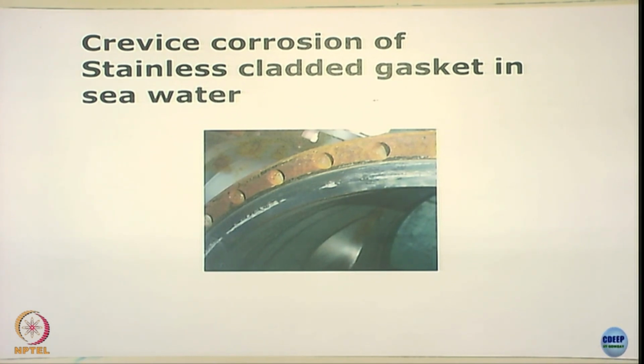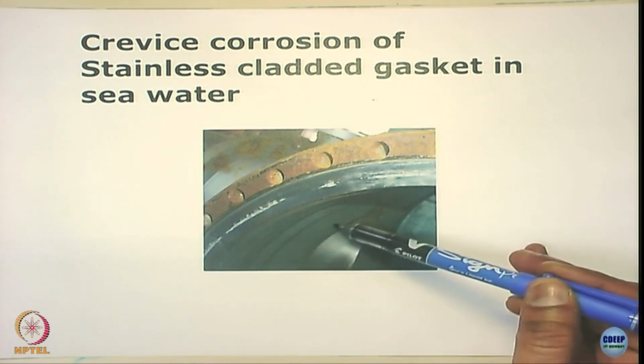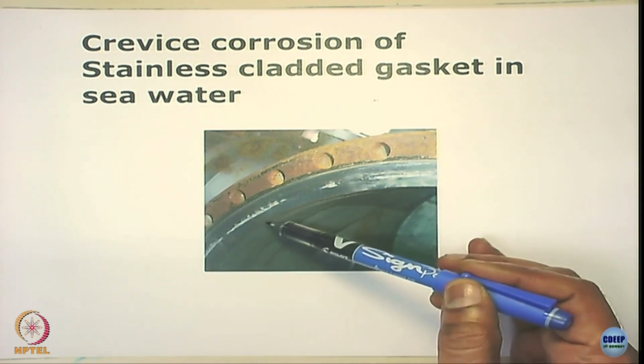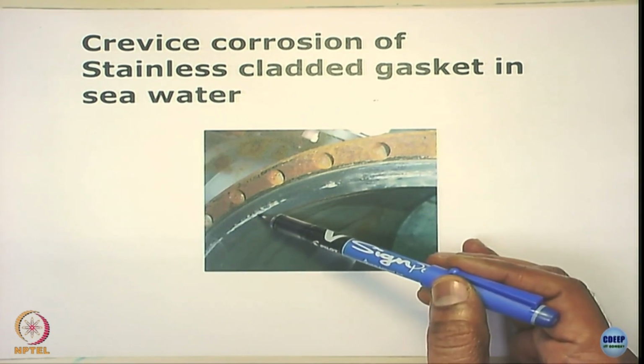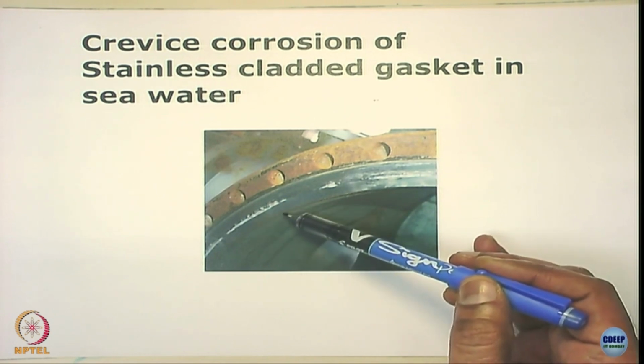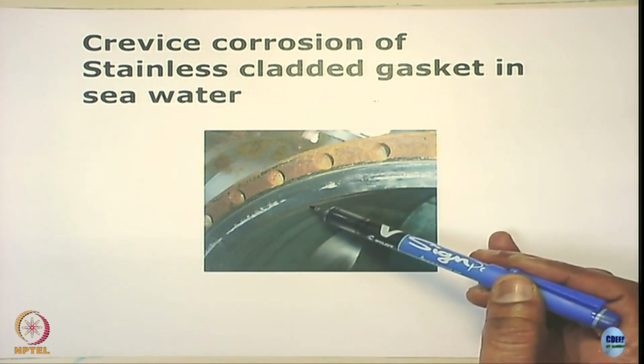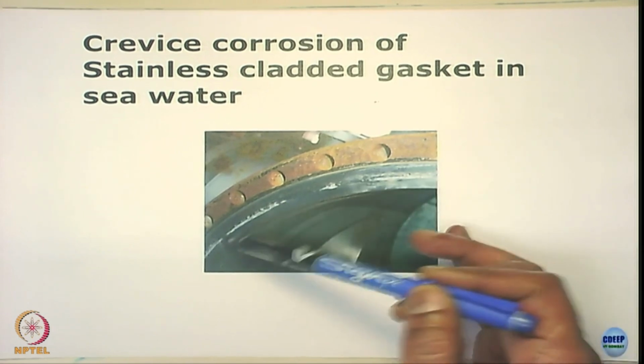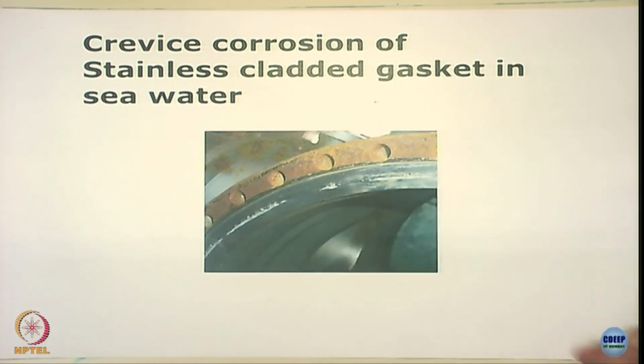Now you see the corrosion, right? The exposure is inside here. The attack is slightly inside. See, this is inside, it is not at the mouth of this joint. So, these are typically what we call gasket corrosion or crevice corrosion, a joint corrosion problem.